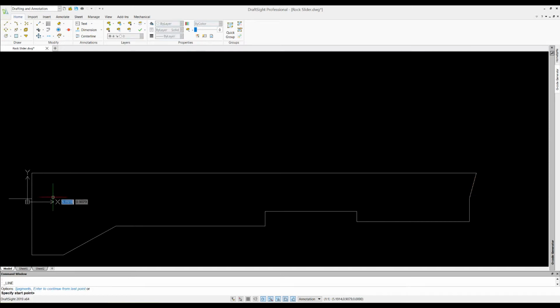So now our first body mount, and this is the one that actually has to stay in our design because we need to get through it for the nut, is what is that? It's 12.5 over, and then from that line down, it's 6.5, and that's to center. So obviously the plate isn't covering the entire hole, at least the way our design is. So I have mine set up. You can see down here, it's specify radius. If you want to do diameter, you just press D, enter, and then we're going to do 2 inch for all of our holes. And you can see it's overlapped there.